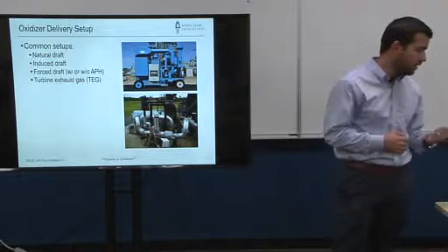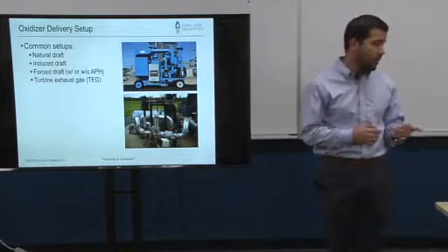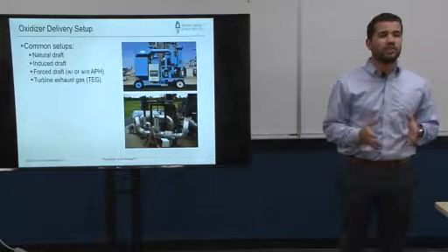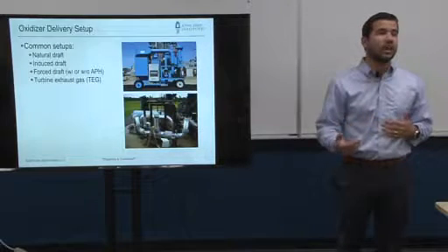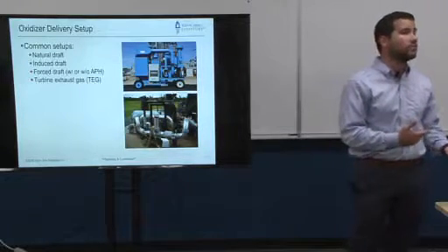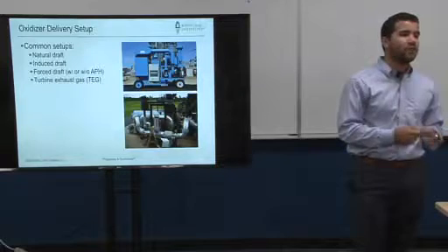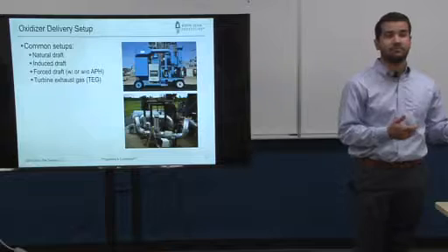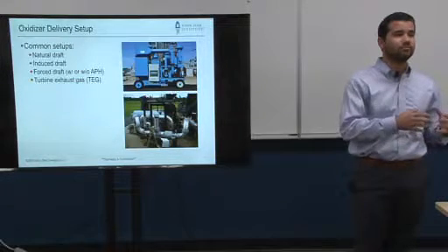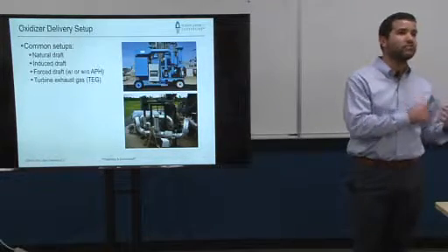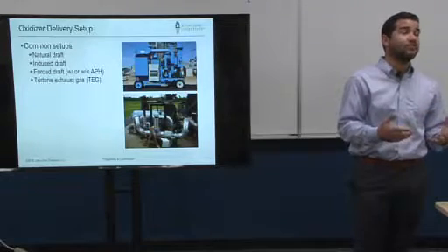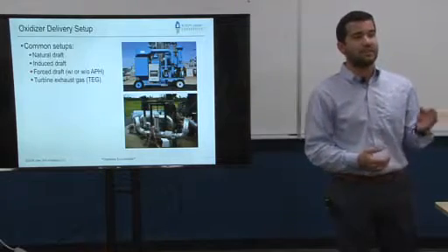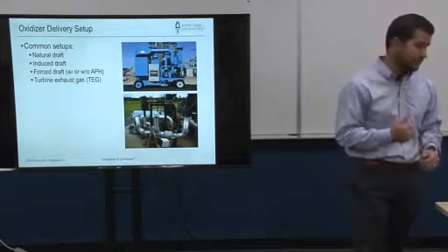And there's actually another application that's kind of neat. We have tested that before. It's called oxyfuel. One of the big drivers of newer technology is lower emissions, lower NOx emissions specifically. An easy way to not have NOx is to not have nitrogen. So they pipe in pure oxygen through these burners and make the combustion that way. If you don't have any nitrogen or any leakage, then you will have pretty close to zero NOx outside of the stack, which is pretty cool.